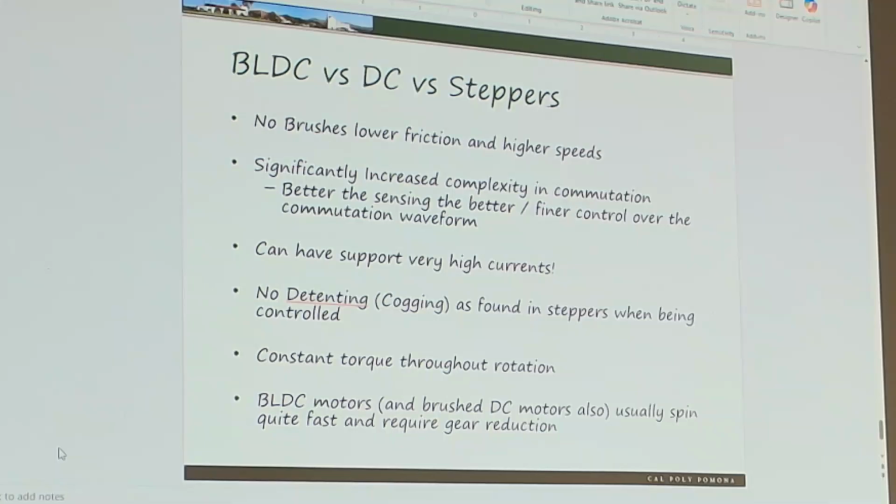But you're using a drill all the time, and you are looking for efficiency on that. You're looking for durability, because if you've ever had a drill for a long time, you've had to replace the brushes. Not that that's a big deal, but, whatever. If you're dealing with something in an explosive environment, then yeah, the brushed motor can spark, and that can cause an ignition point. I don't know. If you're in that kind of environment, you shouldn't be breathing the air. You shouldn't be there to begin with, personally.